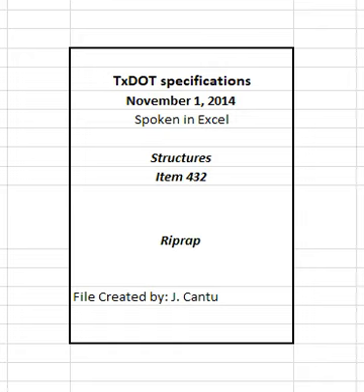Provide grout with a consistency that will flow into and fill all voids. Provide filter fabric in accordance with DMS 6200, filter fabric. Provide Type 2 filter fabric for protection stone riprap unless otherwise shown on the plans. Provide Type 2 filter fabric for Type R, F, or common stone riprap when shown on the plans.